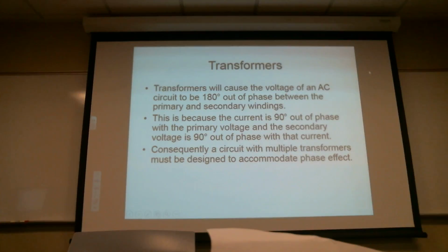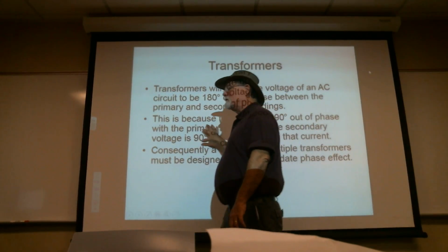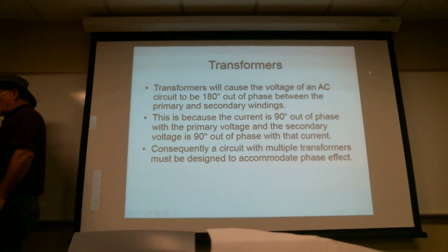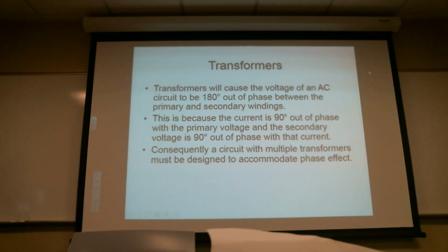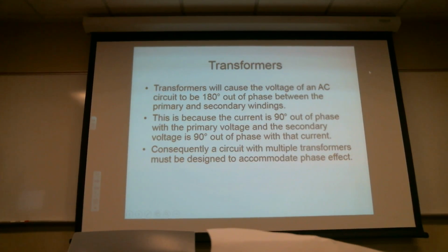Well, that would cause whatever I'm running to not be equally balanced. The three different leads running to each other wouldn't be equally balanced. So if I then drove that back into the compressor, you'd hear the motor humming really weird, doing funny things. So whenever you design any circuit like that, if you're doing multiple stages of transforming, you've got to make sure that you keep things in phase with each other.